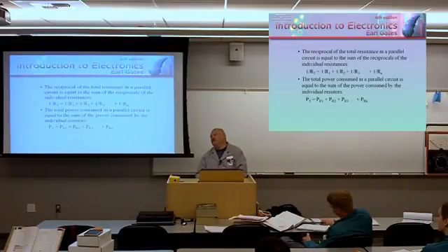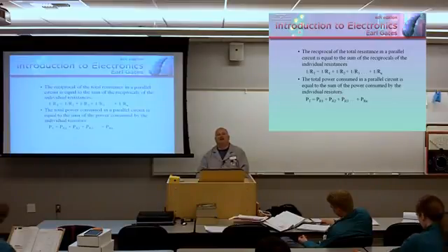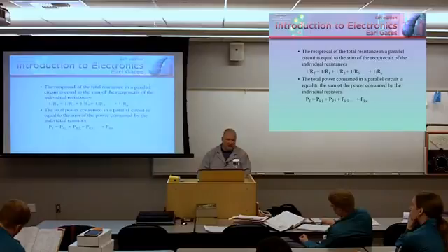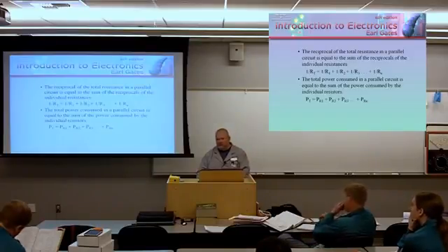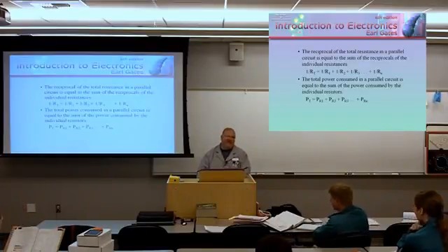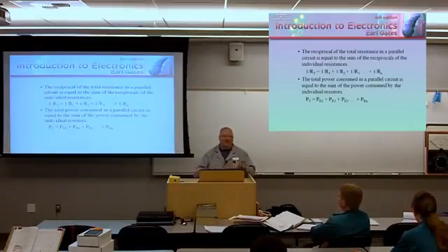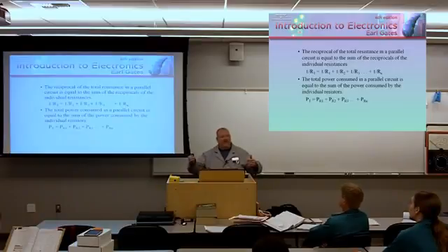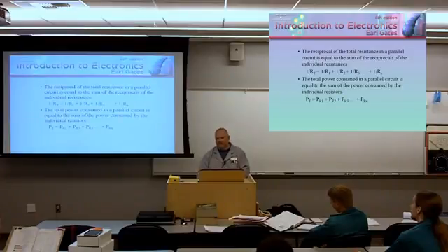The other thing for resistors in parallel, the total resistance will always be less than the value of least resistance. Pay attention to those thumb rules, and your GPA is going to increase drastically because you're going to have something to check yourself against. I don't know if I used the right formula, but I remembered you always said the total resistance will be less than the value of least resistance. My answer meets that. I'm comfortable with that answer and will stick with it.